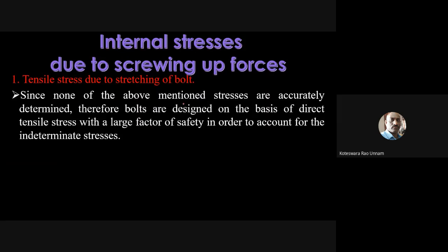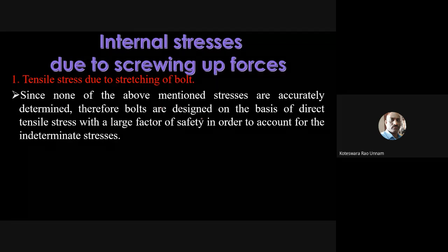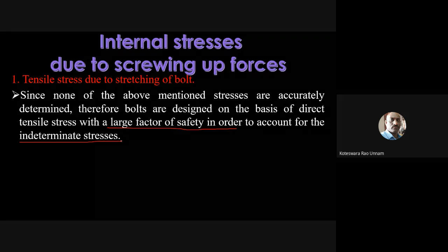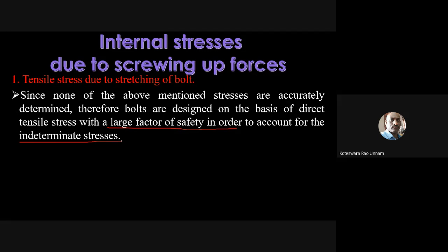Since none of the above mentioned stresses are accurately determined, and I already told you the reasons why we are not able to calculate these stresses accurately, therefore bolts are designed on the basis of direct tensile stress with a large factor of safety in order to account for indeterminate stresses. Indeterminate means the stresses which are not determined. Sometimes it is not possible to calculate all the stresses in case of bolts. Therefore, to account for those indeterminate stresses, a large factor of safety can be used.